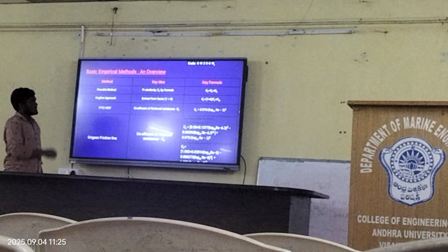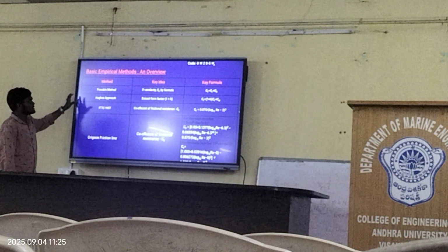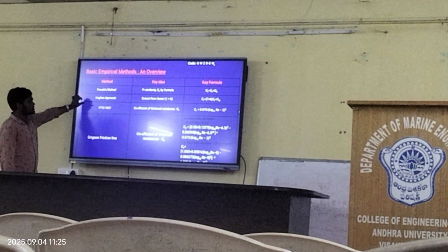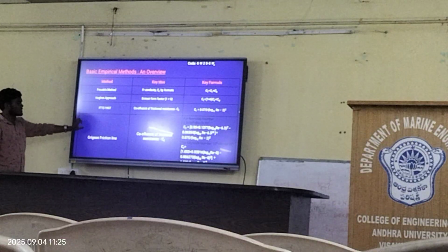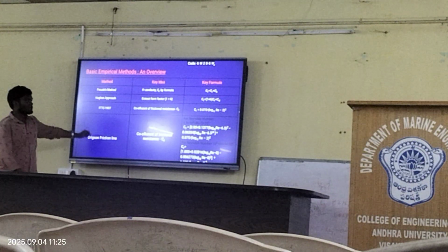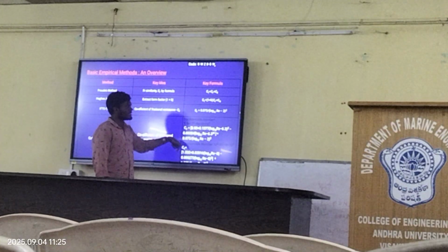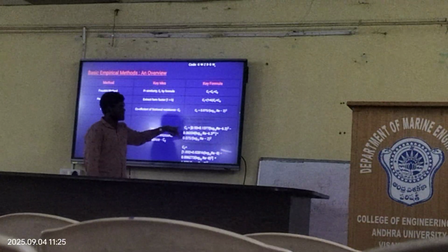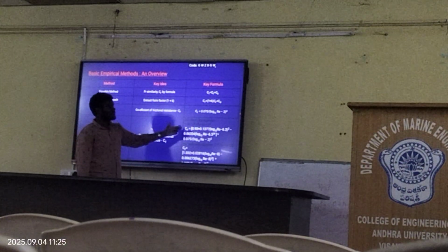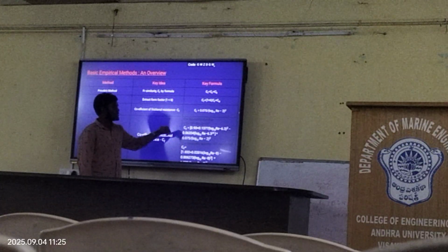Next, these are the foundations of all the empirical methods: Froude's method, Hughes approach, ITTC 1957, Dixon friction line, etc. These are the main foundations that are being used at present in the industry for the calculation of coefficients of friction and pressure, etc.